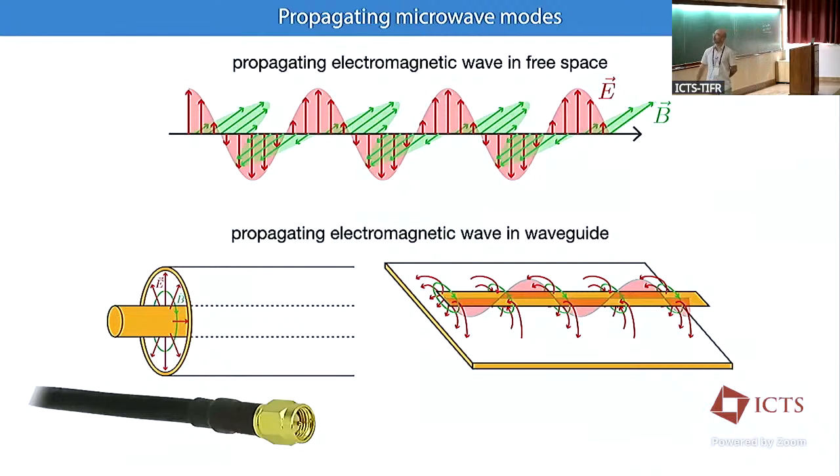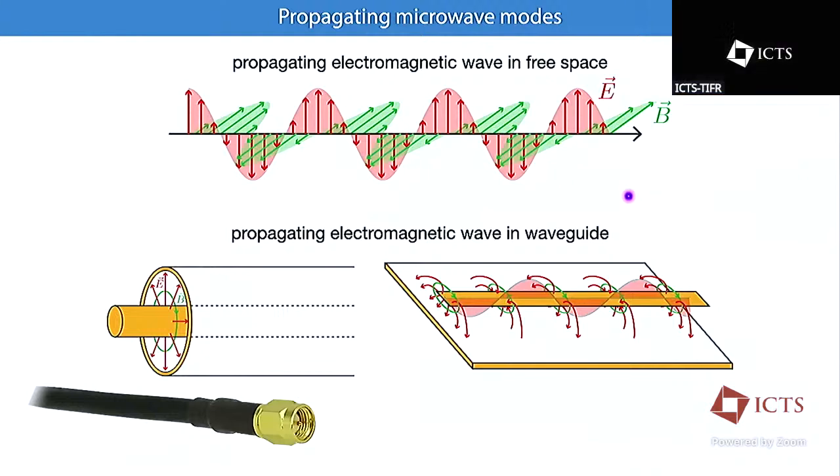But microwave modes can exist in various shapes. They can travel freely in vacuum. They can also travel in microwave coaxial cables or in a coplanar or a microstrip geometry like this. So there are various geometries on which microwaves can propagate. And if we now cut this cable in two pieces, this element will resonate at a few discrete resonant frequencies.